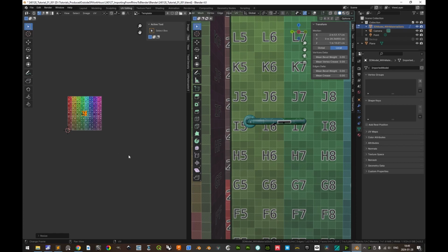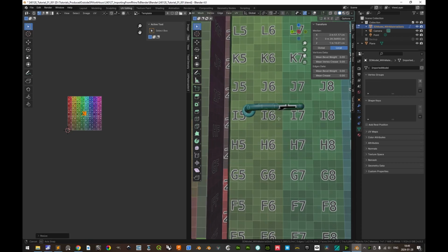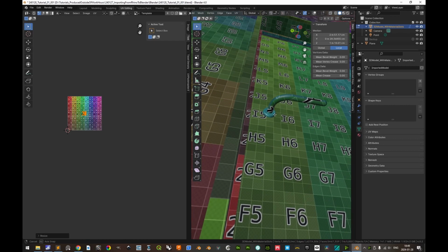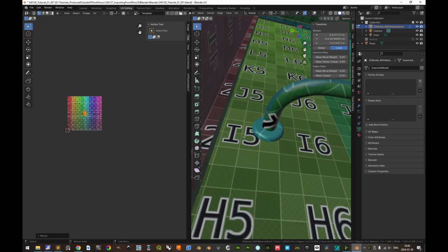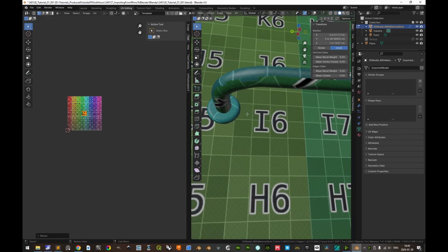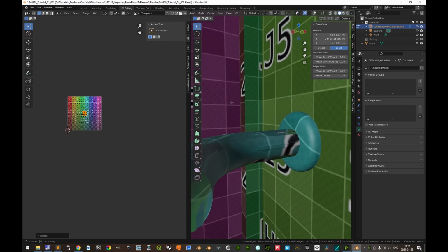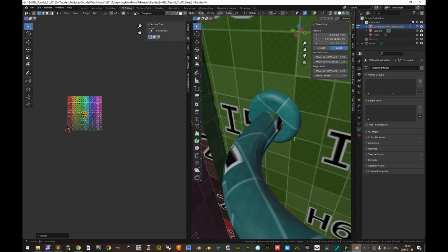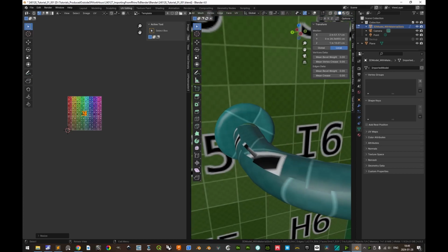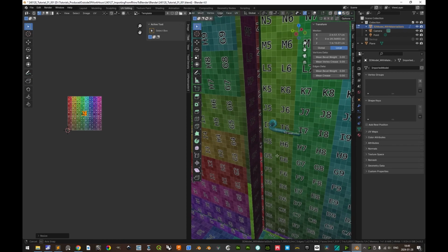And it's quite hard to see here. Let's see here. Do we get any character that shows? Yeah, we can see here that that is still wider than that one. So let's do it smaller. Or is it larger then? Yeah, larger. Okay, good. Then perhaps that size is approximately the same as that size, and that means that this UV island is scaled again. And we see on the backside we have some meshing artifacts, perhaps due to the decimate modifier. It's okay, this will not be shown in the final render.